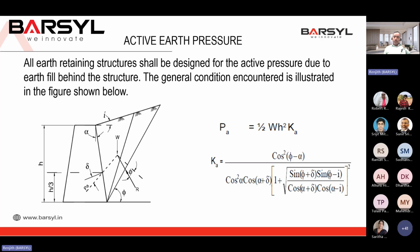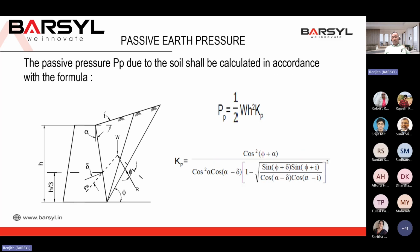If you get the active earth pressure, we know the weight of soil. It is usually 1.9 ton per meter cube, or 19 kilonewton per meter cube. And H is the height of the earth fill which is supported by the abutment. So it is easy to calculate the earth pressure exerted on the abutment stem. That is regarding active earth pressure.